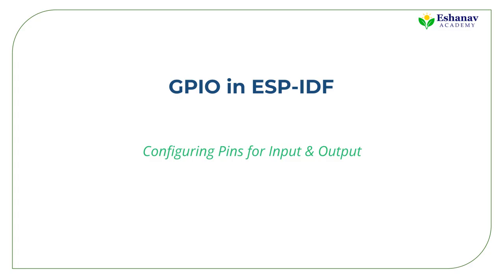Imagine holding an ESP32C3 in your hands with the ability to control LEDs, read buttons, or sense the environment with just a few lines of code. This lesson dives into GPIO, or General Purpose Input-Output, the most fundamental interface on the ESP32C3. By the end, you will confidently configure pins as input or output, understand internal pull-ups and pull-downs, and write simple programs to control LEDs or read button presses. We'll also explore practical patterns for linking inputs to outputs, so you can build interactive IoT projects immediately.